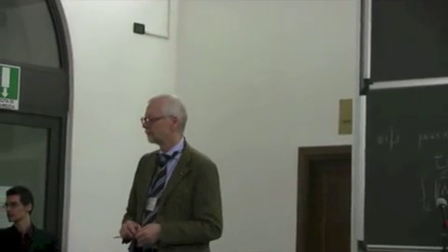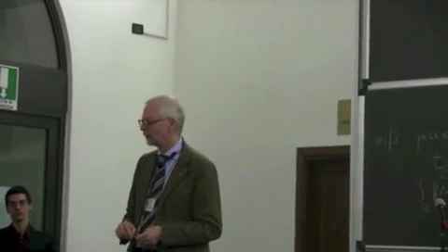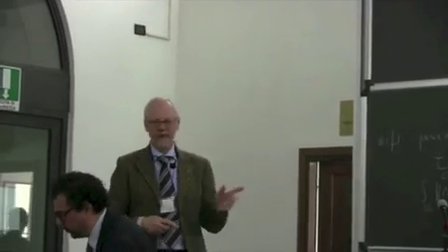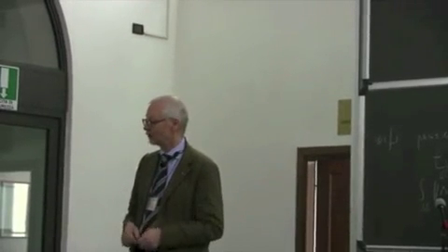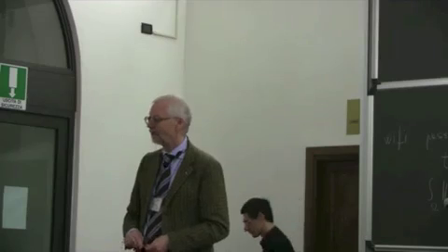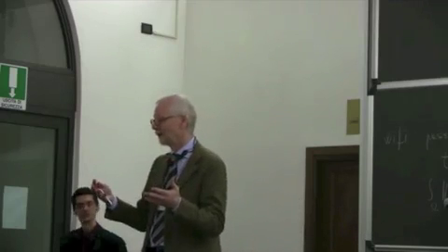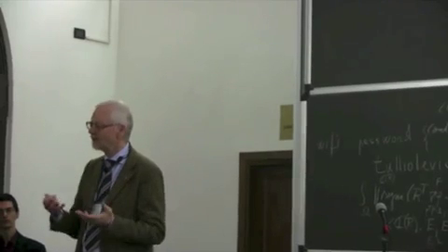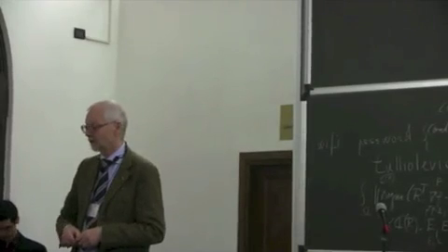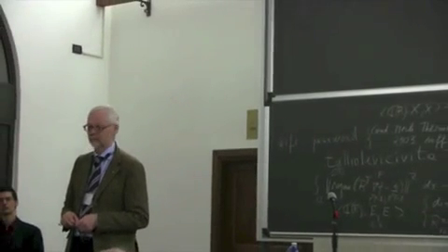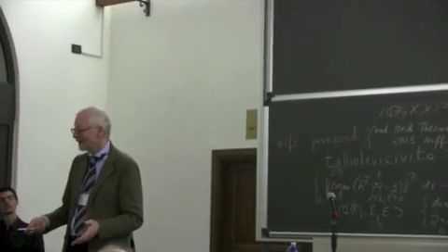Are you saying that you replaced linear theory with some nonlinear theory near the crack tip? No, I don't. And it's linear outside that it works? So no. That's what you mean when you say it works? No. With these solutions, the stresses are infinitely large, but we don't care. And we say, okay, we know that infinite stresses are impossible in real materials. But there happens something in a process zone or whatever you like, and outside this process zone you have linear elasticity, that the singularity is embedded in a linear elastic field, and the failure criteria work. Well, of course, they solve a linear elasticity problem, and it's incompatible with linear elasticity. Who cares? We don't care.